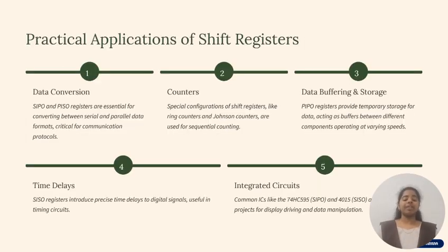Practical applications of shift registers. Data conversion: SISO and PISO registers are essential for converting between serial and parallel data formats, especially for communication protocols. Counters: special configurations of shift registers like ring counters and Johnson counters are used for sequential counting, data buffering and storage. PIPO registers provide temporary data storage, acting as a buffer between components operating at varying speeds. Time delay: SISO registers introduce precise time delay to digital signals, useful in timing circuits.